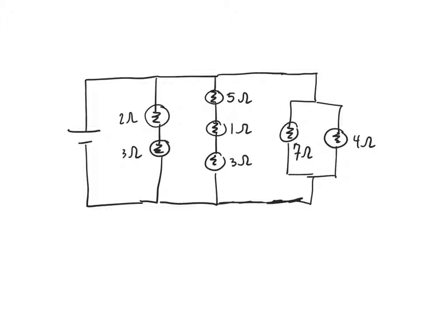Take a look at this circuit. I didn't give you the battery yet. It doesn't matter what it is. Let's say it's a 9-volt battery for now. First, tell me in each area what's going on. In this first section, what kind of setup are these two bulbs in? Series. Why series? Because they're in a line, there are no junctions between them. From this bulb to this bulb, there's no branch occurring. So these must be in series.